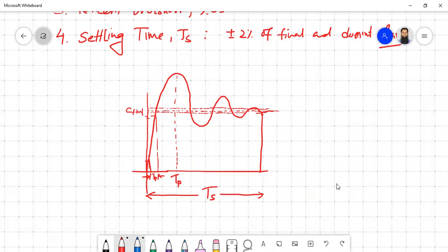And what is percentage overshoot? It is the amount of the rise that you gave, C max, compared to your steady state value. Let's say you're supposed to have a steady state value of 1.5 ampere, but initially it is rising up to say 4.5 ampere. So percentage wise it will be 300 times more. This is how you have to express the percentage overshoot.